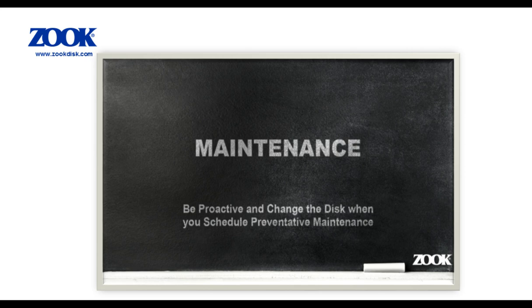There are no specific maintenance tasks that can be performed on a rupture disc device, with the exception of pre-torqued holders. If a metal rupture disc device is taken out of service and the disc removed from its holder, it should be replaced.